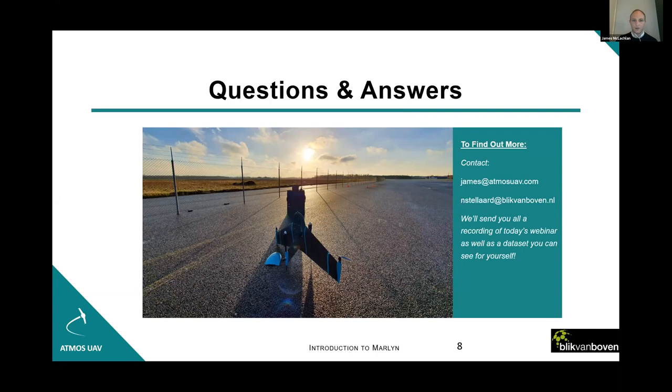Is it possible to do post-processing on flight position to enhance the accuracy of the data? Also from Krishna Subianto. So what I believe you're asking here is it possible to include in the post-processing the position of the drone, so the angles of the drone? So yes, this is possible. We have our own autopilot software and hardware, which basically means that we have all the data after the end of every flight. And as Norbert would have told you, one of the streams of data that you use in the GeoTagger is your autopilot file. So within there is all of the angles of the drone.